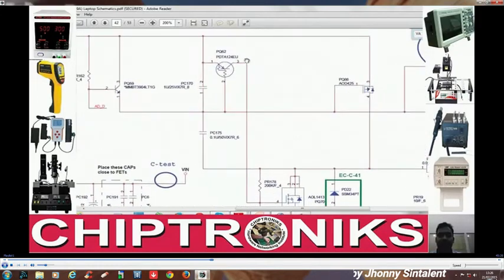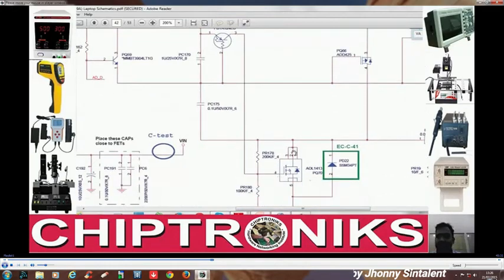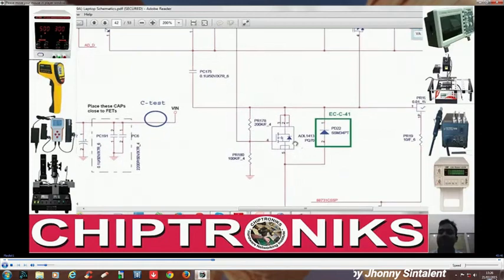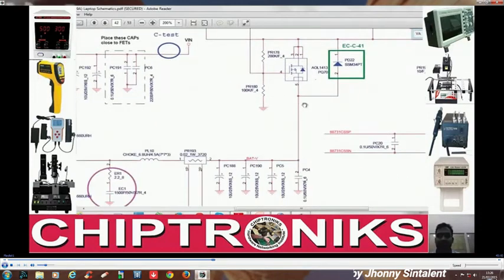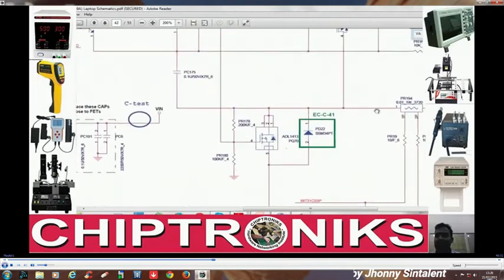It will get turned off because this VA1 is now present over here, and at the source Vin, which is close to VA1, is present, so VGS is close to 0. In a P channel MOSFET VGS has to be less than 0, so this switch will turn off and the battery is no more connected over here.